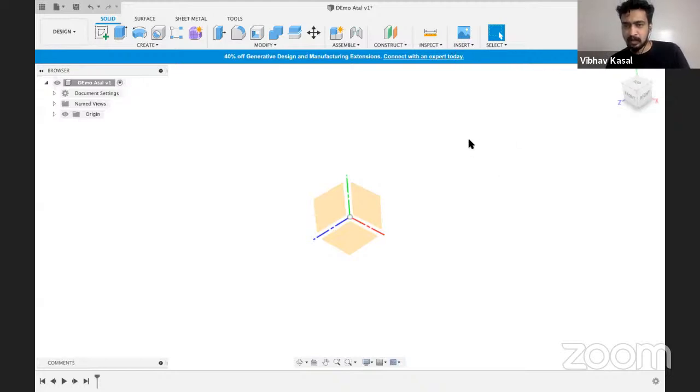And how to laser cut. For laser cutting, you have to generate a file that you can send to the laser cutting people. This could be a simple vector graphic or an SVG file, like how you have JPEG and PNG for images. For lines and vectors, you have SVG. So SVG is one thing, DXF is another, and then you can even send a PDF, a printed document file, but the PDF should not have a lot of gradients and images. It just needs to have the lines that they will use for cutting. So they will only extract the lines from the PDF and cut.